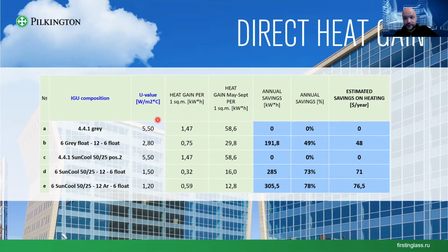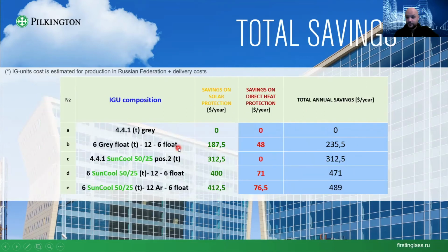And even if you're sitting under the air conditioning, it can heat you up. So the temperature of the inner glass is also important here. And that is the temperature given by the U value. But by solar factor, of course, also by direct sunlight. But the U value also does matter.